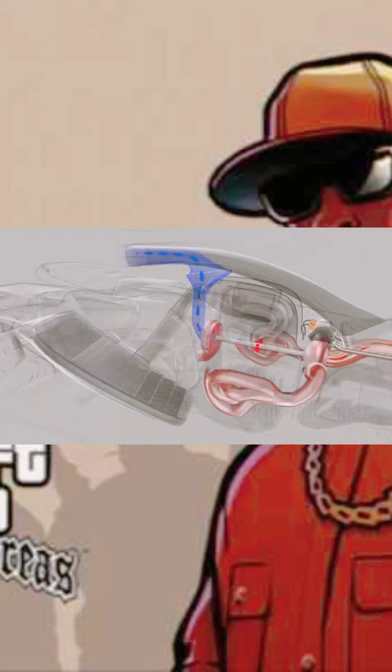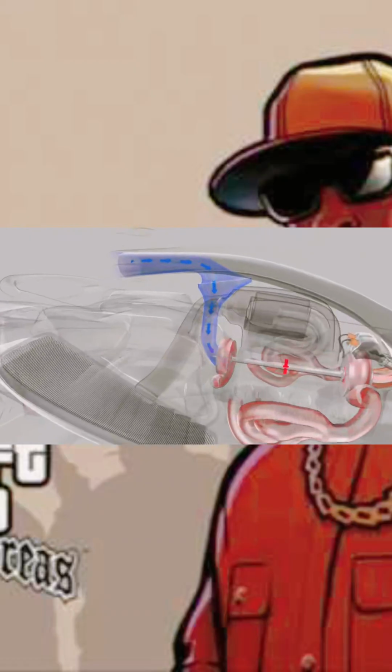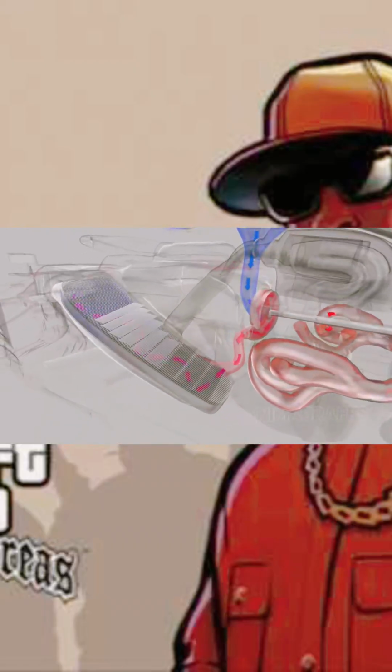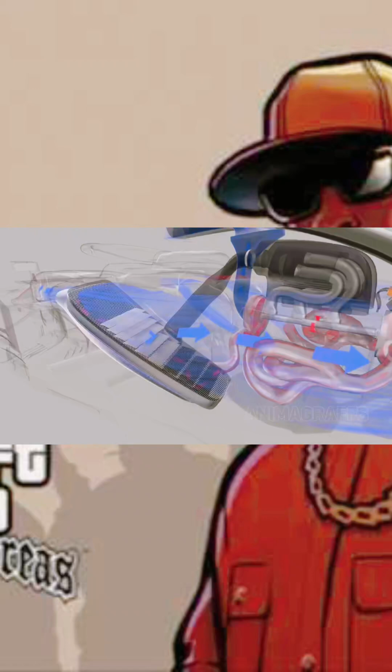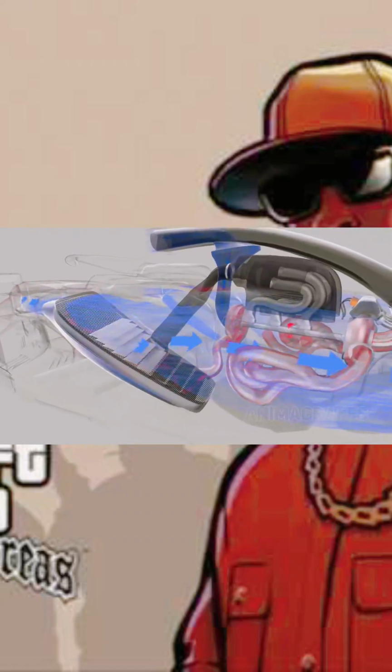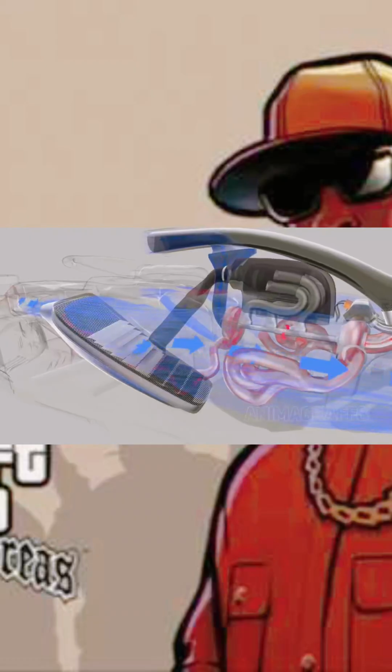The compressor draws air in through an intake duct mounted in the roll hoop above and behind the driver's head. Hot air leaves the compressor towards the intercooler. Side pod air rushes by the intercooler's tubes and fins, cooling the compressor air inside.